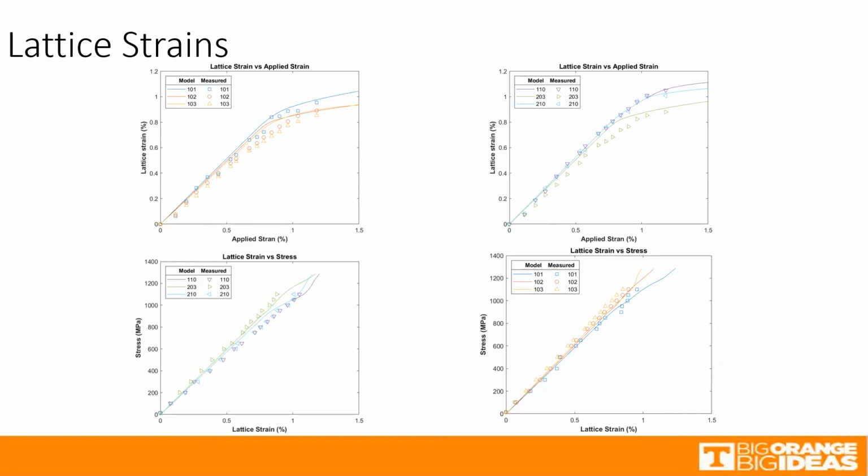The overall fit of the lattice curves is not as good as the previous macro curve. This is mostly visible in the elastic region, which is primarily decided by preset elastic tensors and does not change during the course of the model. The yielding regions show better agreement. Unfortunately, we do not have the experimentally measured 100 and 002 planes, which would show the activity of the basal and prismatic subsystems and better represent partitioning of lattice stresses and strains.